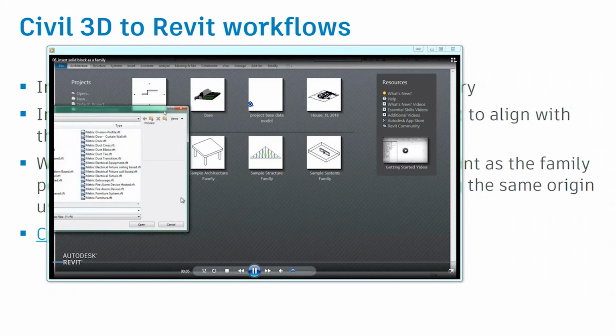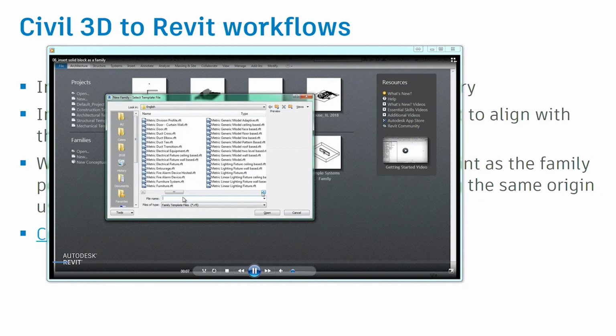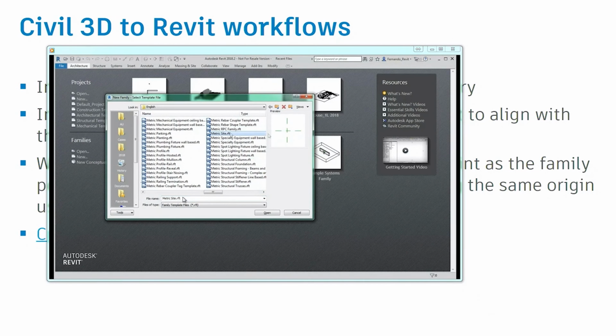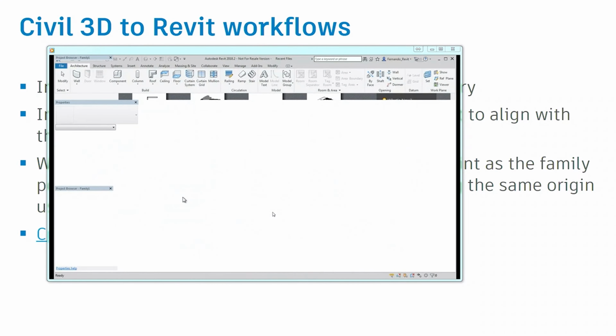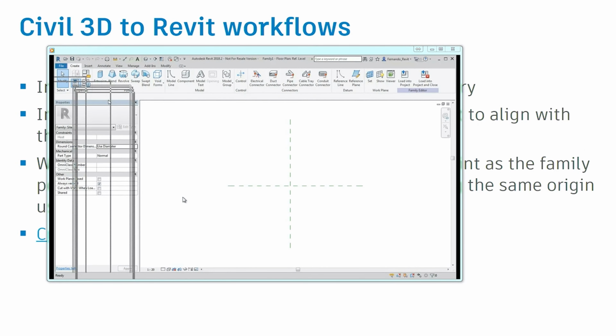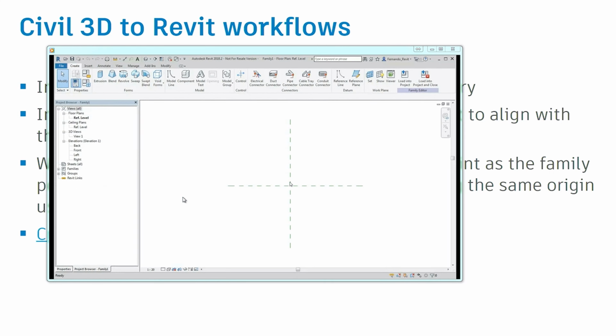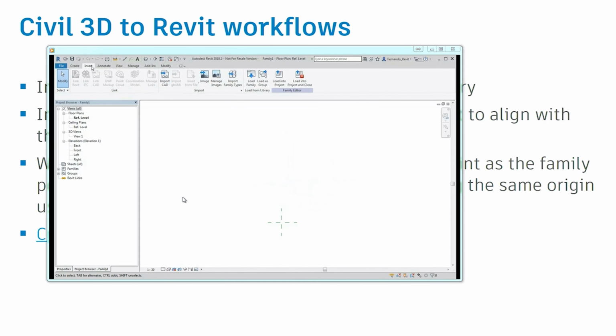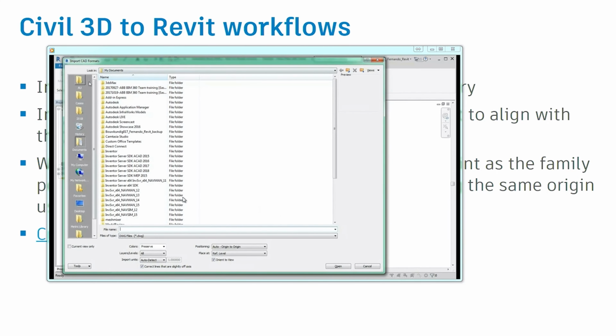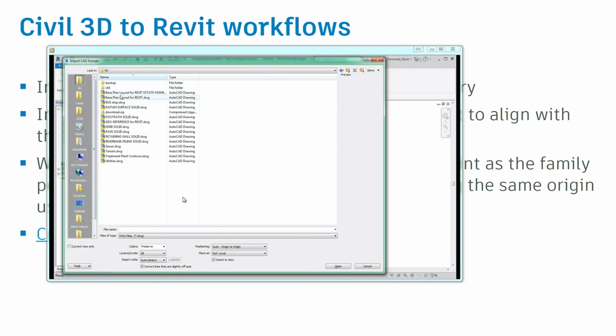So what we're going to do is create a family in Revit. It's a family in a category, and in this case we're going to use the site category. The families don't recognize coordinates. So we're going to use the insertion point of the family that's in our template, grab the file that will create that surface, put it there, and align the origin of the family, or of the block, with the center of our family, with that insertion point.